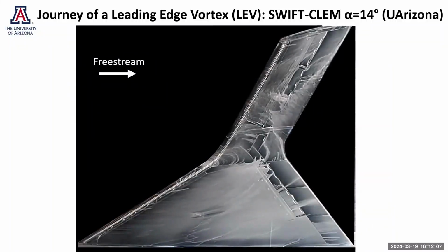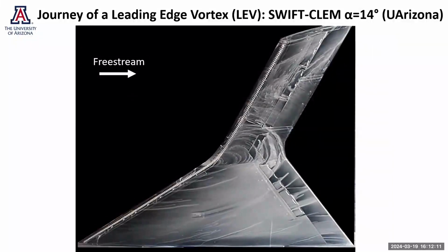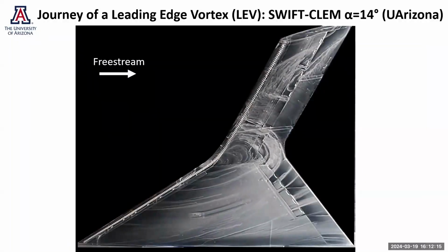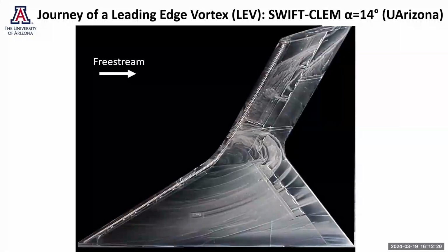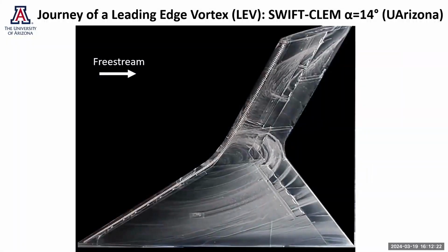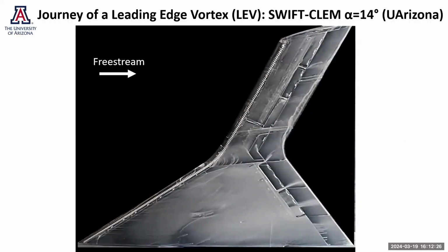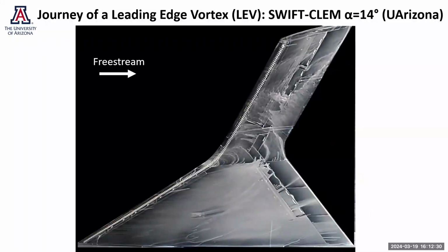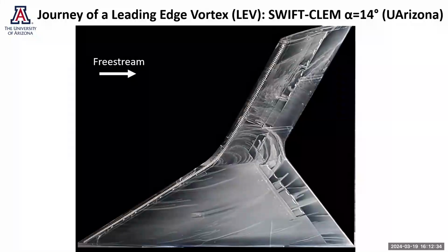So you can see how this mixture flows along the wing, and that shows us different structures that can occur on the wing. So at this angle of attack, we see that the fluid that is over here, which we call the inner main wing, has this rotary motion and is entrained and goes on the outer side of the wing.